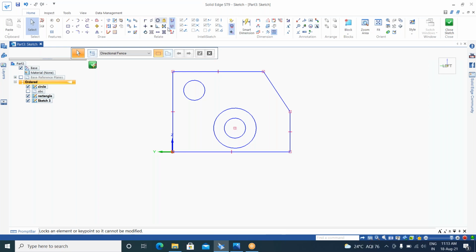Okay, so here in the beginning itself, we have given maintain relations. If the option is inactive, we don't get to see all these relations. Every line will be individual and separate, without any relations. I will draw once again without a relation.